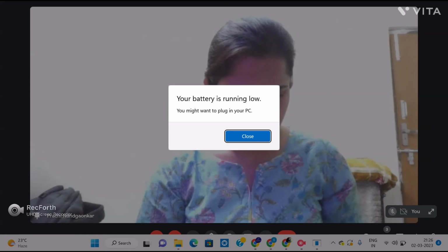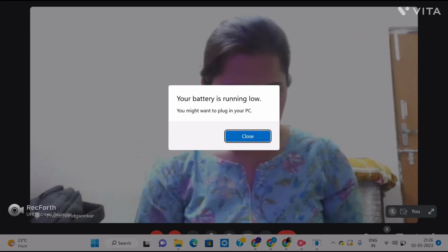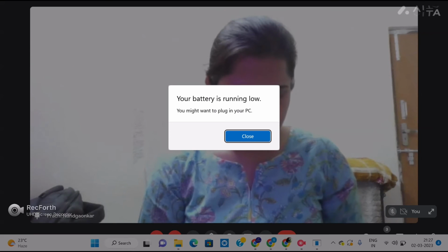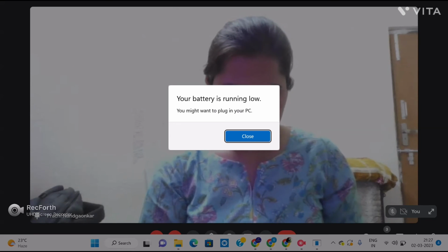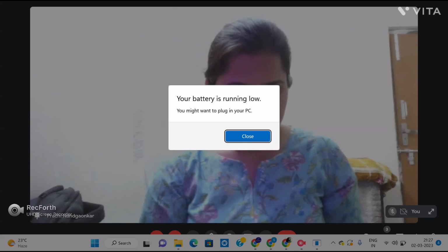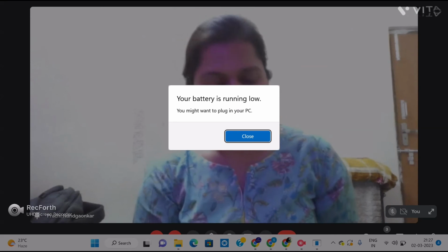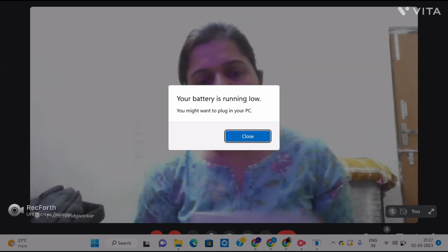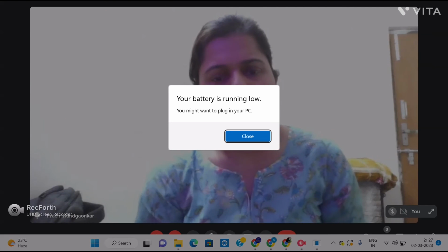Yes, sir. And there you mentioned it is an initial block. Actually, it must be an always block. Yes, sir, it's an always block. So just now you mentioned that always is synthesizable, and now you wrote initial. So there is a mistake there. Yes, sir. I will correct it your way.